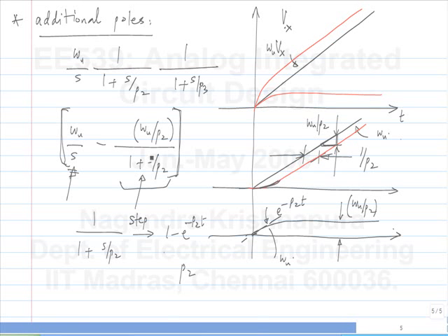The time domain analysis gives you a better intuitive feel for what happens. It looks like it is delaying the feedback, right? So that means that it is probably taking you closer to instability. What we have established so far is that if the pole is at a lower frequency, it adds more delay, so it's worse. If there are more poles at a given frequency, each pole adds additional delay, so that's also worse. We will do the frequency domain analysis and see where the poles must be.